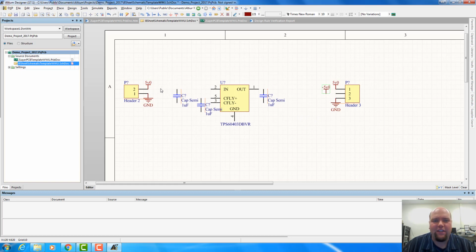How do we actually wire these things up? The way we connect signals electrically in a schematic is either by labeling two things the same thing. So in this case, this pin here and this pin here are identified as being physically connected together because they're given the same label name. The other way we can do it is by drawing a wire. We can draw a wire between two things to show an electrical connection.